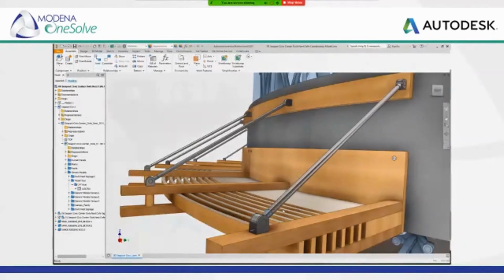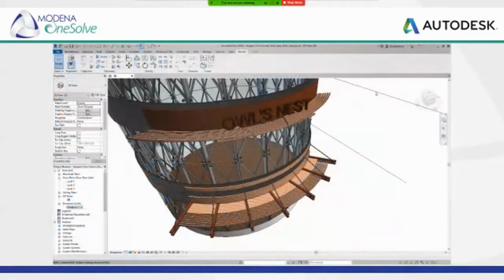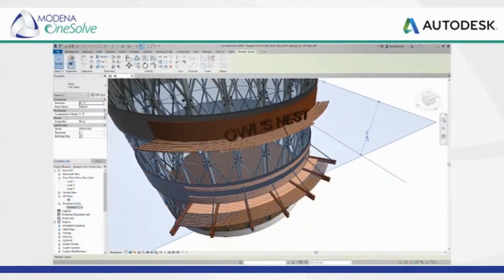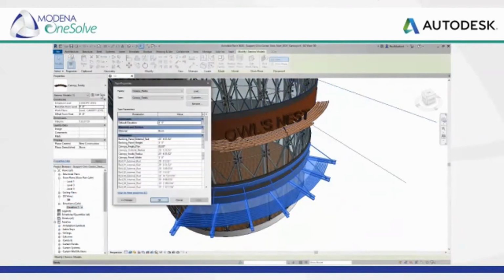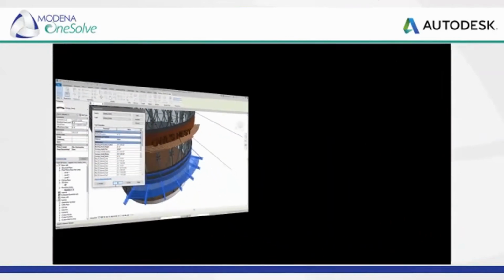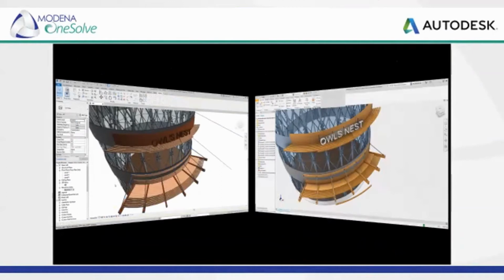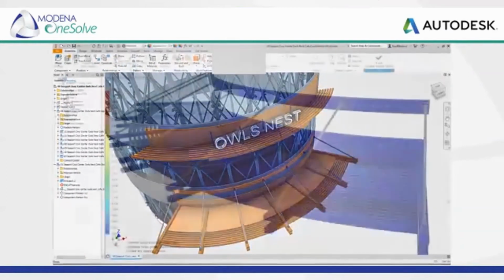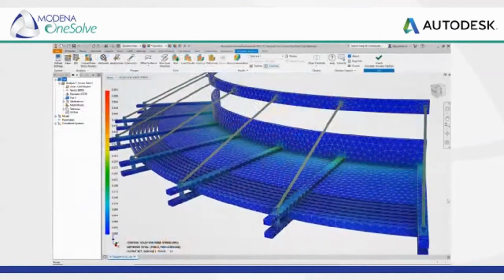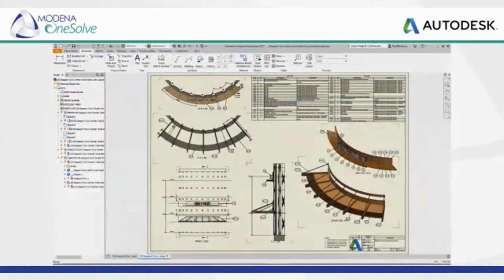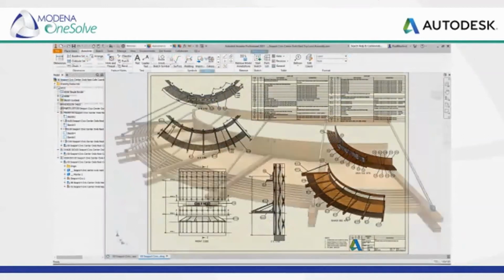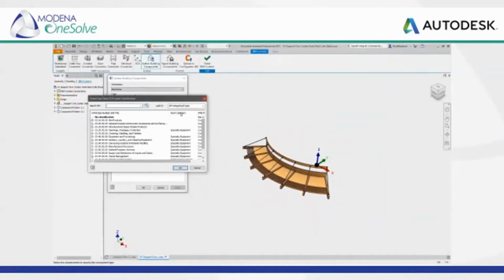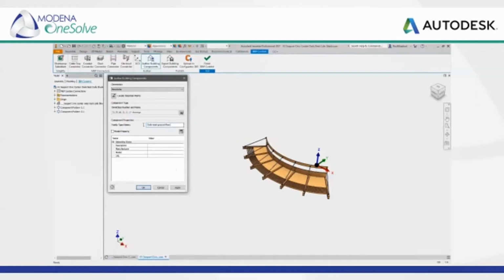Changes during the design process are inevitable. When the REVIT model changes, we'll need to update the Inventor model to suit. Because the REVIT model is referenced into your Inventor assembly without file translation, any changes to the REVIT project will also update inside the Inventor assembly. A change to a design in Inventor is a change everywhere your design has been referenced, automatically updating all downstream uses of your design model, helping you coordinate your work and keep up with change.